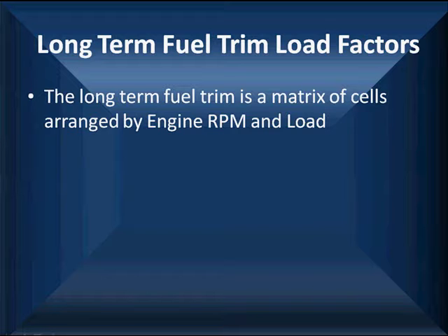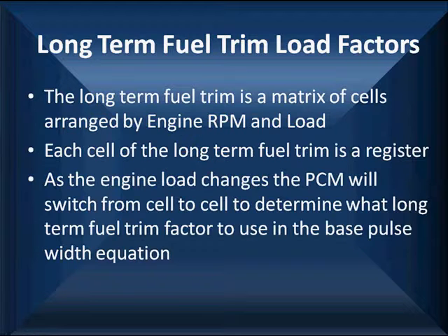Now, long-term fuel trim, load factors. Long-term is not just a reading. It's a matrix, a group of cells arranged by engine RPM and load. Each one of these cells has a specific long-term number in the register. The register is a place in memory. Now, this is a little bit confusing to some people, but as we go through it, you'll see it.